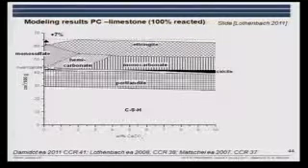But when we add the limestone, we will have more ettringite and we will have hemicarbonate develop, and later monocarbonate. And at a certain time, we don't use up the calcite. You will also see that, given that we know the molecular volume of the phases, we actually can model the porosity.